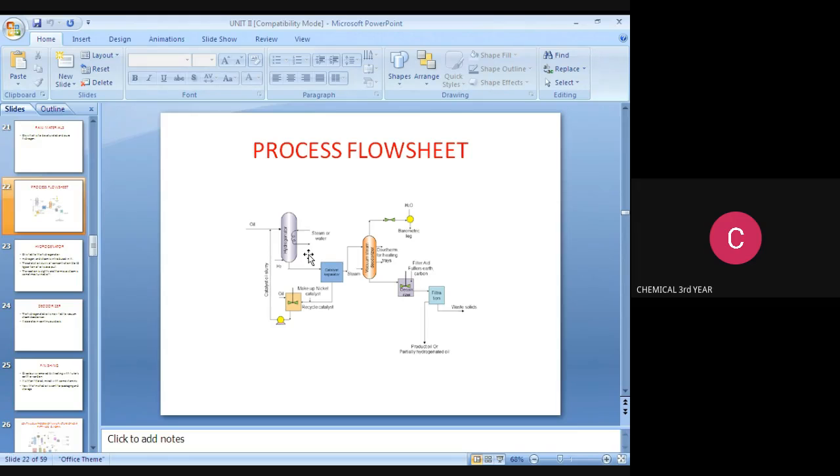The catalyst is passed to another stir tank. We are adding the oil, which is pumped to the catalyst slurry in the hydrogenator, and then it passes to the catalytic separator. It is passed to the vacuum steam deodorizer. In this vacuum steam deodorizer we are adding steam and Dowtherm for heating. Then the bottom of that vacuum steam deodorizer goes to the decolorizer.